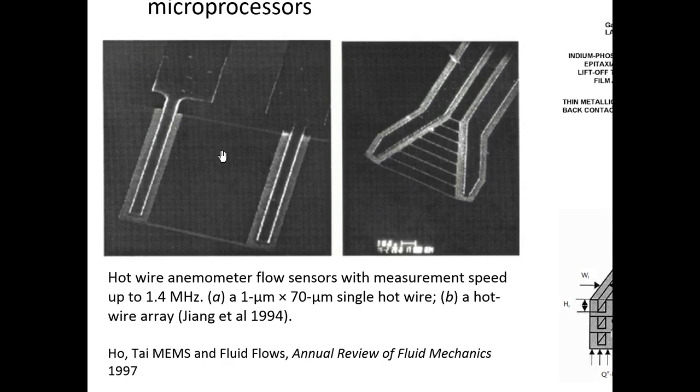How a hot wire anemometer sensor works, it's a way to measure flow, by the way. It's a way to measure gas flow. You have two wires. Let's say this one is heated and this one can be used as a temperature sensor. Now, when you have flow this way, heat energy is being advected from this heated element to this element, which is the sensor. So at high flow rates, you're going to sense a temperature here, and at lower flow rates, you won't receive as much.